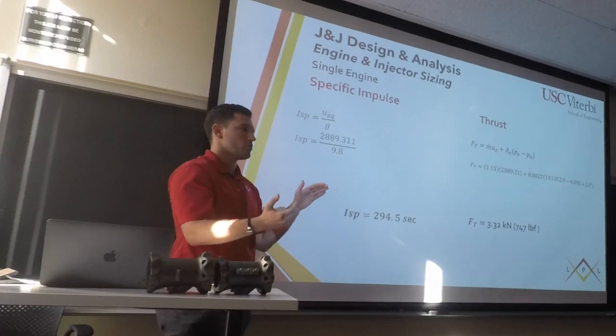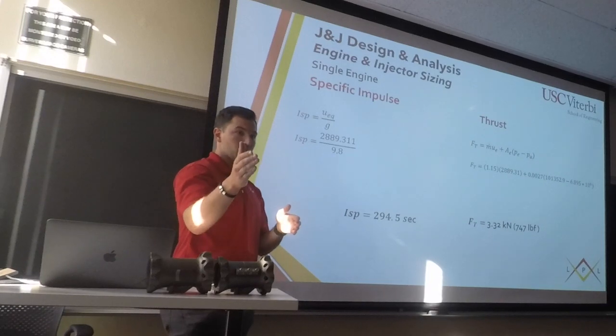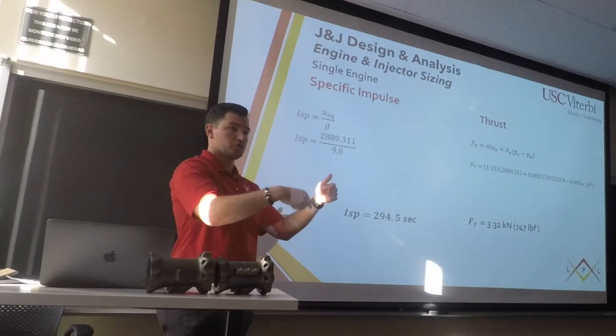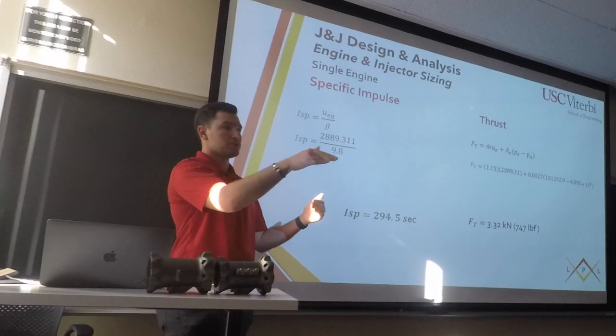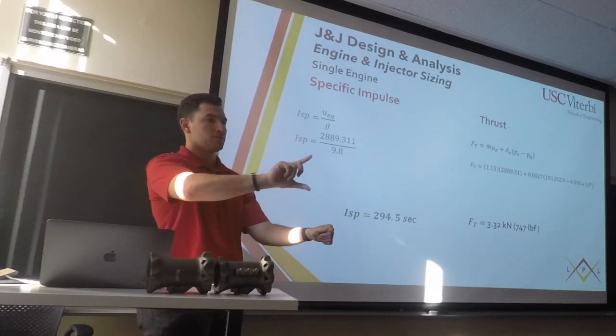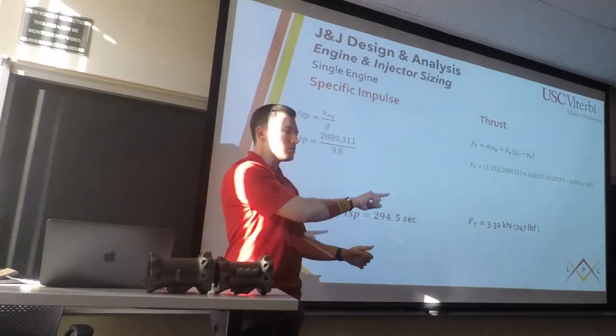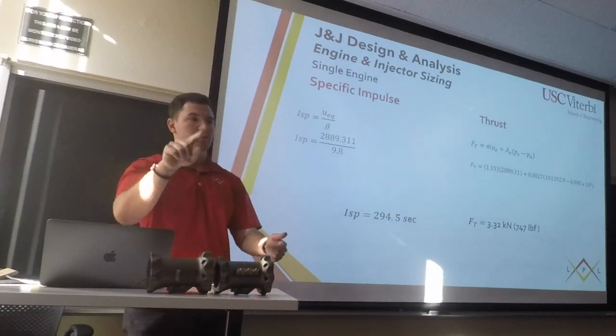So when you're overexpanded, you have a shock wave because it wants to be what it is outside. It generates a shock, the pressure jumps, and then you end up having an expansion fan, right? It ends up being a series of shocks and expansion fans until it ends up equaling outside. And that's why you'll see they keep going, because it's slowly going to what it is outside.